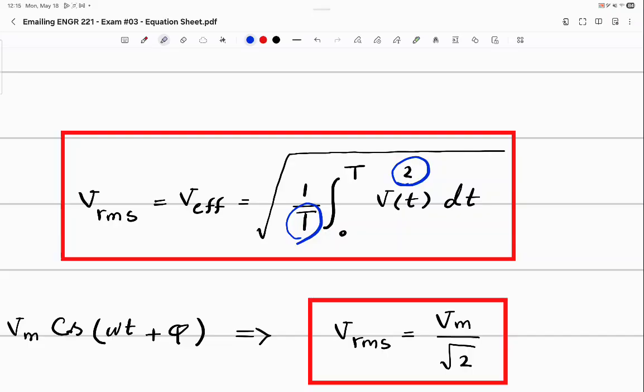Because the signal squared should be integrated, not the signal itself. So don't go for the area. And one more thing: I have seen students that whenever a signal is given to them to find the RMS or effective value, they just divide some number that they find about that function, for example the height of the function, by √2. What's wrong with that method?